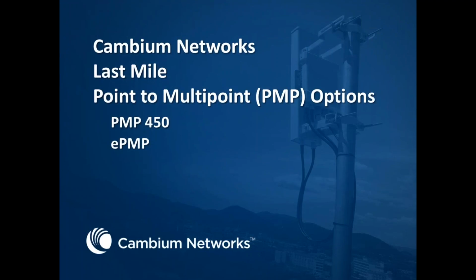One thing about the 650 before I go on: the 650 also has a feature called DSO. A lot of customers are kind of leery about using an unlicensed radio for backhaul. The 650 has a feature in it called digital spectrum optimization. If you set that up in a particular channel band in a spectrum and somebody bursts into your channel, the 650 surveys the entire band, and if somebody bursts into your band for whatever reason, the 650 will actually switch to a cleaner channel to make sure that your transmission is always the best that it can be.